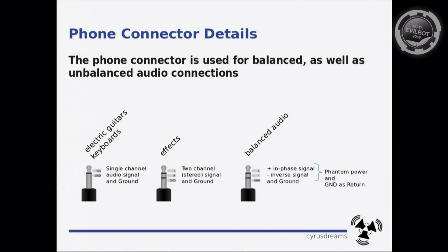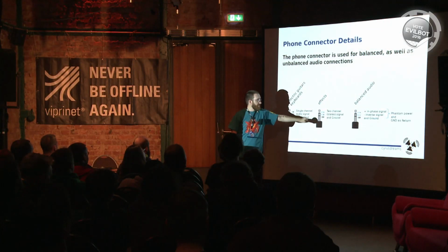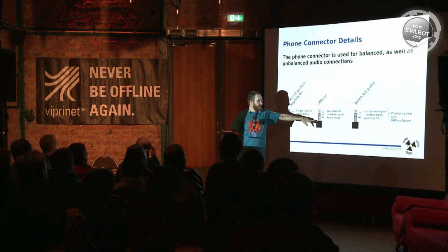And then you find this on brand new electric guitars. That's the standard connector your electric guitar will plug in. And also modern keyboards still come equipped with TS connection. Or you can have this as an effects chain, so it's two audio signals, where one might be send and return and reference to ground on the sleeve, or it might be the stereo signal that you have on your headphone plug. And interestingly, the professional headphones still use the 1/4 inch type, so it's the thicker one, and it's a stereo signal, left, right, ground.